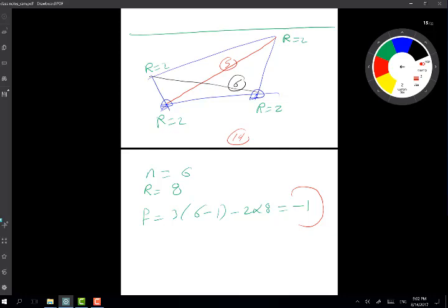And even when civil engineers try to calculate forces in the arrangement or in the structure with this redundancy, they find it difficult to use the statics equations: the sum of forces is equal to zero, and the sum of moments is equal to zero. To calculate the forces or the reactions in the members, in this case, they have to use an extra material-based equation called the compatibility equation.